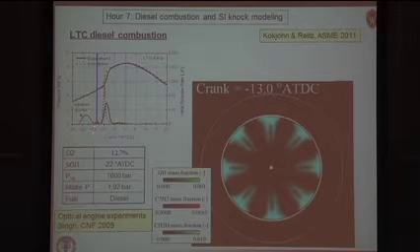This is now right here in the low temperature combustion region, or the cool flame combustion as it's sometimes referred to. The liquid has now disappeared because we are at the end of injection and it's more or less vaporized. There's a little bit of evidence of some liquid left, but it's vaporizing, and we're starting to see the first stage combustion.